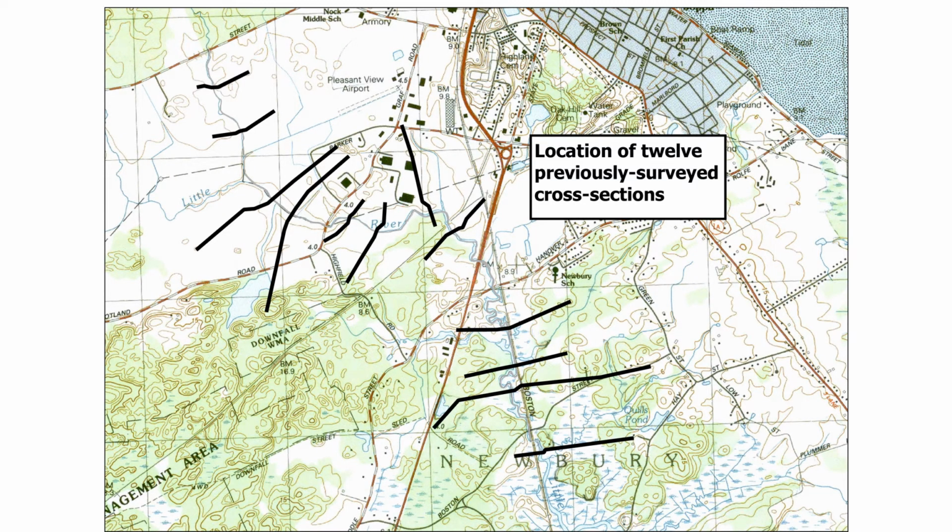Now, the digital elevation model does not pick up anything underwater, so there were some cross sections from a previous field survey of another engineering firm that were available, and I was able to merge the underwater part with the digital elevation model, and that was done in HEC-RAS Mapper.